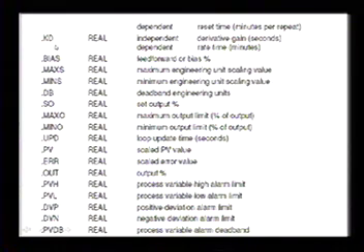Then you've got your KD, real value, your bias, your max S, the min S, and then you've got your DB. The max S and the min S, those values, I don't think you can actually change, but you can change the max O, min O. And what these are is you can actually put a limit on the output. You've got to check a little box to make sure that you can do this.